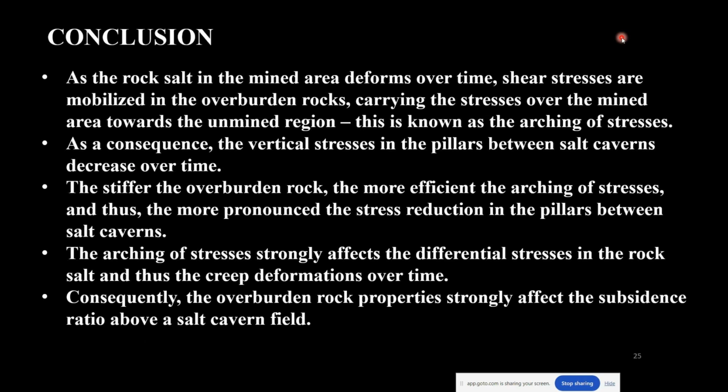And consequently, the overburden rock properties, which strongly affect the effectiveness of the arching of stresses, strongly affect the subsidence ratio and the deformation rates above the salt cavern field. So it is not obvious, but the properties of the overburden rock also affect the deformation rates over time.